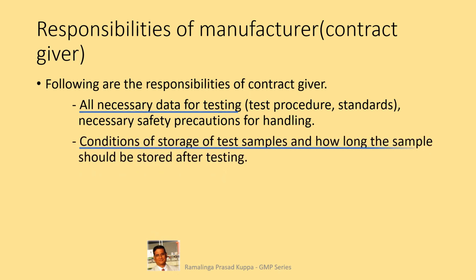Conditions of storage of the test samples and how long the sample should be stored after testing. Certain materials are sensitive to ingress of moisture. They have to be handled under nitrogen atmosphere. Handling of such materials should be communicated to the contract laboratory adequately to get reliable results.